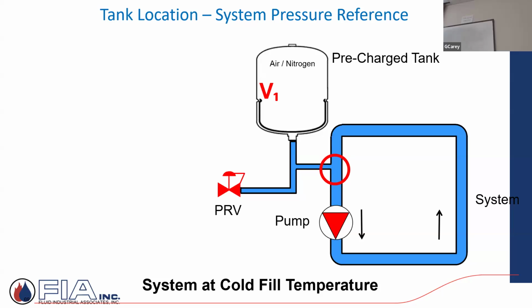So we start looking at commercial drawings and the systems that you guys have, with your air separators, your expansion tank, your base mounted pumps, for example, you're going to almost always see that the tank ties in right near that air separator. And then I go to the suction of my pumps and I go out to the system. Perfect. It's exactly what we want.